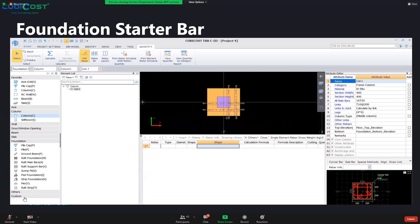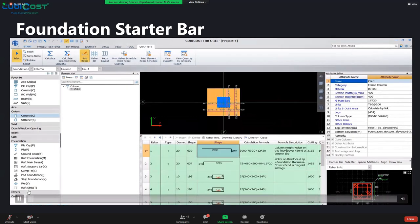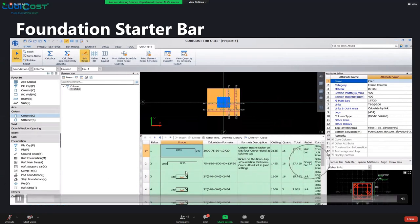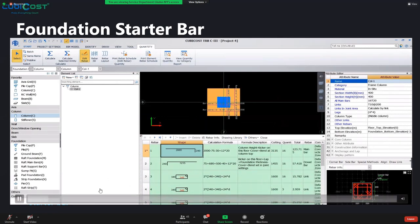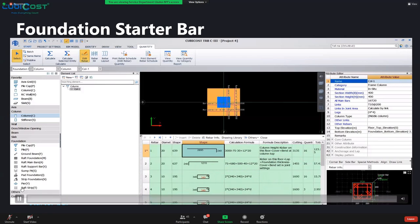So as you see here, I have drawn a column and a pile cap. As you can see here, by default, it will actually generate a dowel bar, which is your starter bar. By default, it will automatically generate the dowel bar for you. So in this case, if you are not using T20 bar type, basically your starter bar and your main bar use different types of bar, how can we actually adjust this?